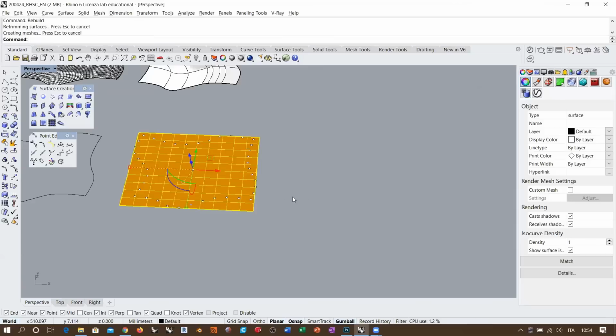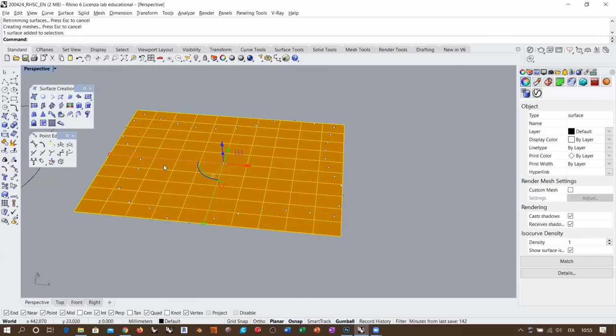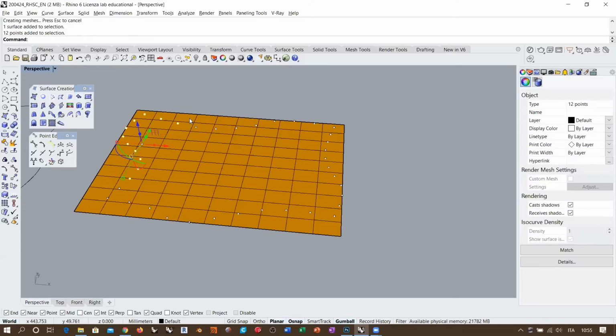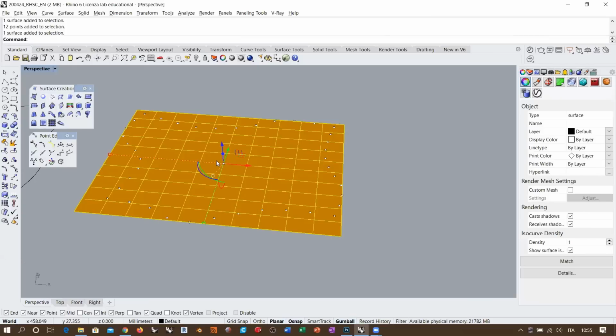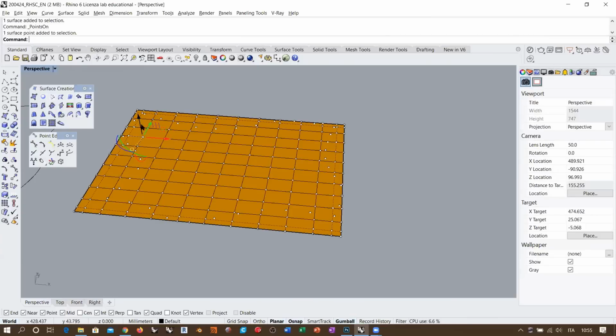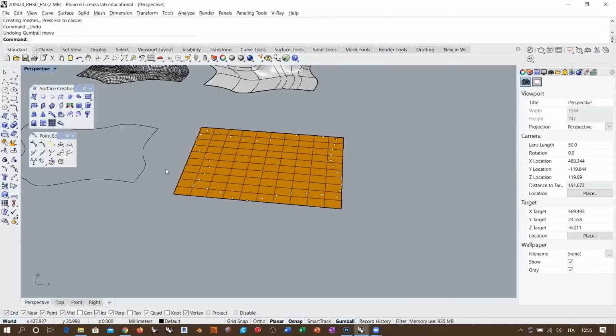This is the fitting plane with a rebuild that the patch command is creating. Then, if the patch detects that all these points are not at the same height, it starts to take the control points of the surface and displace them in order to have the surface fit, or pass more or less through the points derived from the input objects.